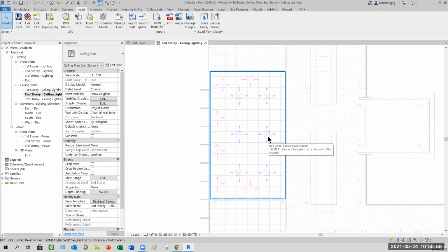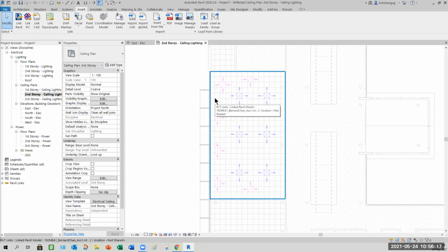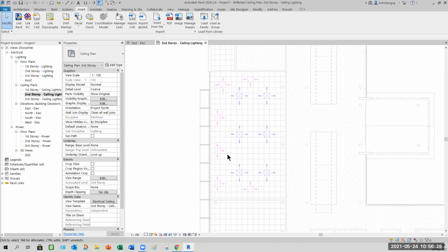If not, people complain certain areas will be very cold, certain areas will be pretty warm. At least we try to have the whole area even. Here it's warm at daytime because this is glass, so no choice. Normally it'll be warm, but not super hot. At nighttime, all the surrounding temperature will be the same because the return is here, it draws the aircon back. So these are things we need to understand, at least for a basic understanding. Okay, so this is the thing we have now.